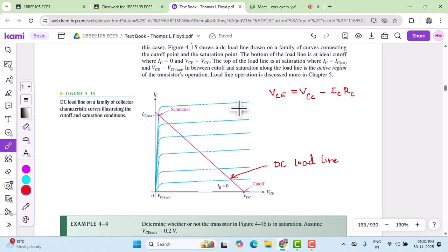And it's an important BJT parameter that we need to examine, and also look at whether beta DC is dependent on any other factors or not. So beta DC is not a constant. It depends on several factors. First and foremost, it depends on the collector current, and it also depends on the temperature.